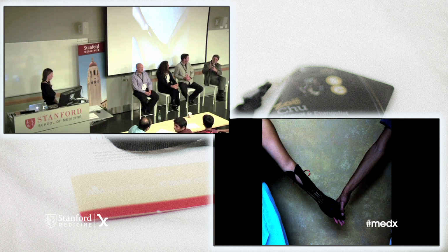But it's got little wedges cut into the knuckles and into the shape of the palm, so that when the cords cause it to contract, the fingers curl and the palm wraps and you get a really interesting grip. So that's an example of that kind of thing, where you're using it to determine the angle of the various bends. They act as springs to open the hand back up, and they provide actually a more biological feel as well.